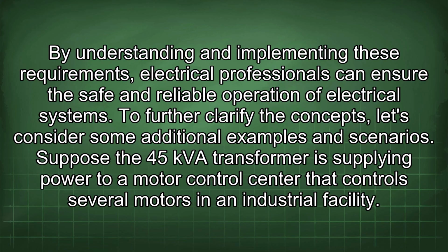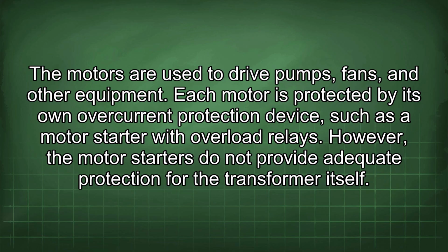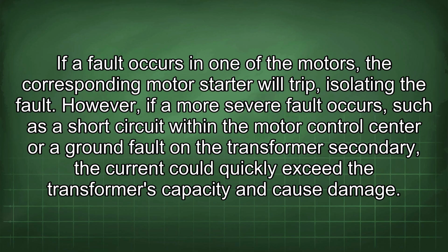Suppose the 45 kVA transformer is supplying power to a motor control center that controls several motors in an industrial facility. The motors are used to drive pumps, fans, and other equipment. Each motor is protected by its own overcurrent protection device, such as a motor starter with overload relays. However, the motor starters do not provide adequate protection for the transformer itself. If a fault occurs in one of the motors, the corresponding motor starter will trip, isolating the fault. However, if a more severe fault occurs, such as a short circuit within the motor control center or a ground fault in the transformer secondary, the current could quickly exceed the transformer's capacity and cause damage.